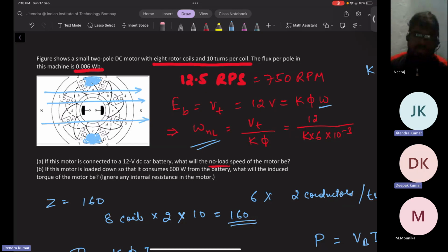Sir, if there will be four poles, then that conductor will come in the active region. Yeah, definitely. In that case, that conductor will come in the active region. But it is not certainly guaranteed that in a four-pole machine all the conductors will come under the influence of your field MMF. Why? Because the width of this north and south pole can also be reduced. It will be so small that some conductors are not getting linked by the field MMF, right?